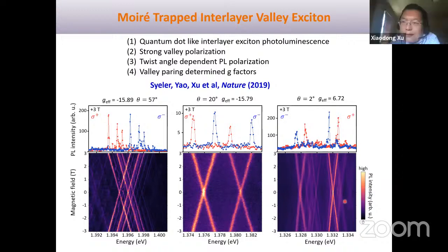We haven't done in-plane. We tried, but it's a very difficult project because of the challenges. When you say apply an in-plane field, imagine these are really narrow, really thin samples, a couple of nanometers, and there's the challenge of how to apply an in-plane field across a couple of nanometers. Out-of-plane is much easier to do. You just need two gates on top and bottom. Well, I was just thinking of two side gates that are like 100 microns apart, and you just apply. Yeah, that way it's very inefficient. You don't see anything basically. I see. Okay. But with out-of-plane, it's very efficient.